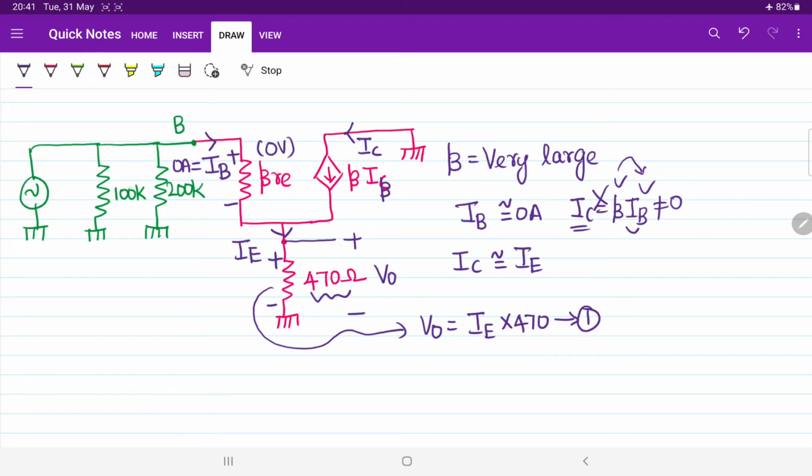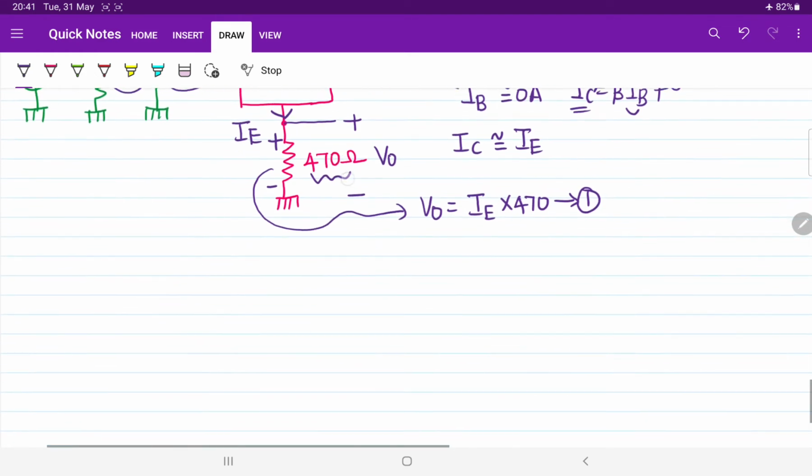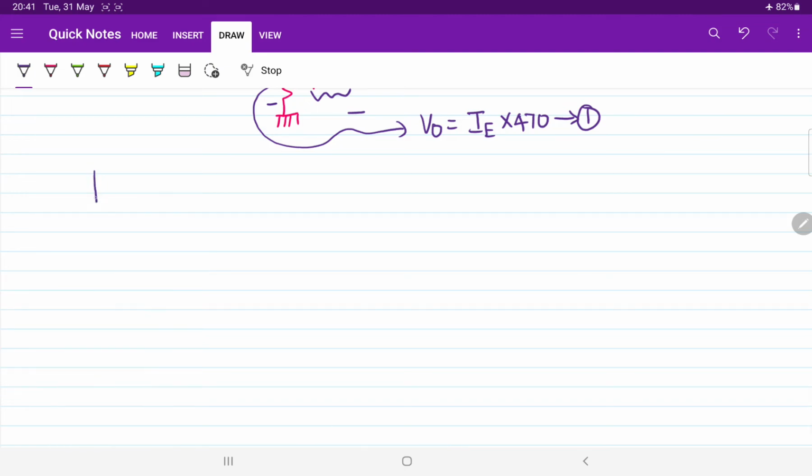Next, see there, this 100 kilo ohm and 200 kilo ohm both are in parallel. Yes, sir. So if I reduce them, we can compress like this. Just observe, almost all the circuits will be the same. You can easily solve the questions. I am just compressing it. And I am directly writing that 100k is parallel with the 200k. That is the representation of parallel resistor. Okay, sir. Since the value of current will be 0, now see there. Now this is going to be your input voltage.